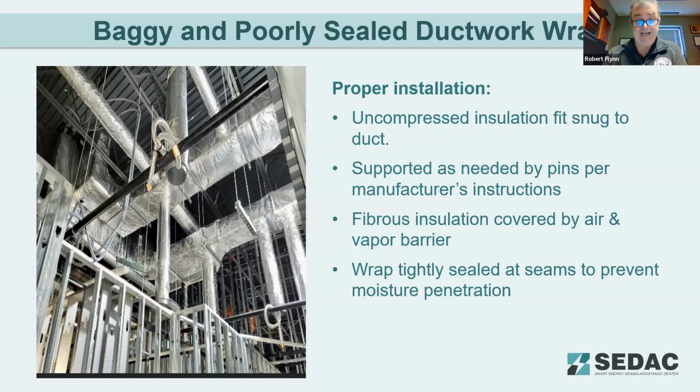So I would say yes. If it was me, I would say yes. The duct should be sealed before the insulation process occurs. And the energy code does cover that as well, in the duct installation section. I'm not remembering the section number off the top of my head. But duct needs to be installed per the manufacturer's instructions, and then the insulation goes on top of that. So whatever ductwork you install, it has to be air sealed as indicated by the manufacturer's instructions.